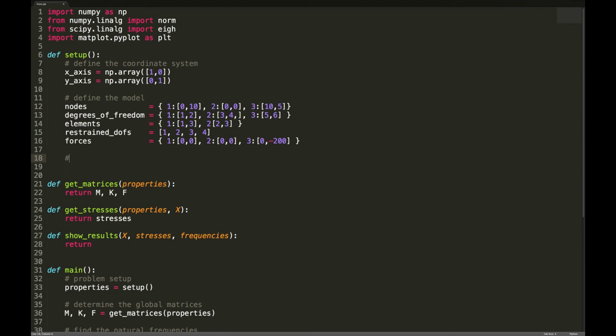The next thing is to look at the material properties. In this case, we're using a carbon steel. It's AISI 1095 carbon steel, also known as spring steel. Why? Because it's typically used in springs. Pretty high yield strength, very high toughness, tends to be very elastic.